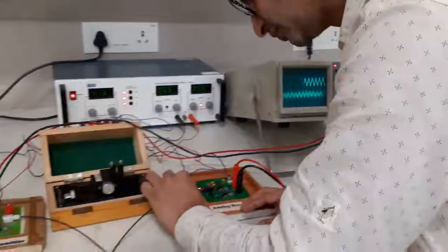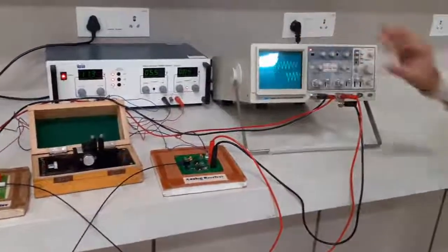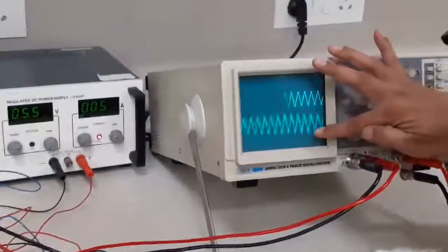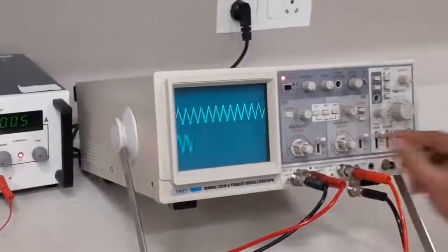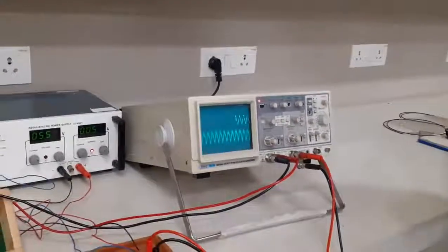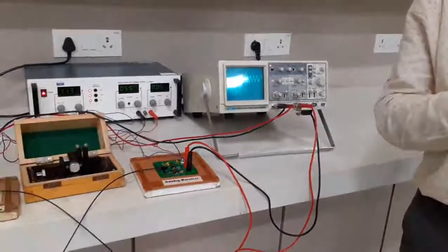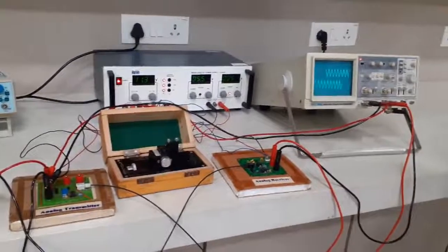So we have connected 1 meter fiber in this, and we have just calculated that at the moment my output is 1 division, 2 divisions, 3 divisions, 3 into 0.1. So my output at the moment is 3 divisions multiplied by 0.1 volt, that is about 0.3 volt. After traveling 1 meter of fiber, my output is 0.3 volts.